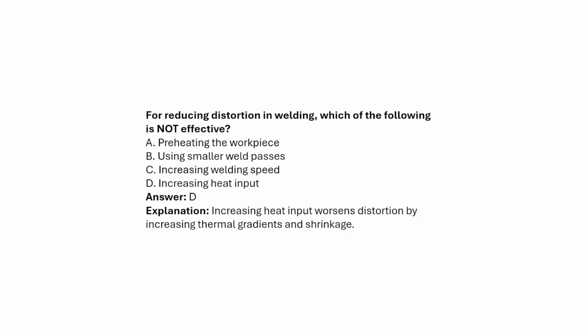If we increase the heat input, that will result in an increase in the distortion. So the answer will be option D. Increasing the heat input worsens the distortion by increasing the thermal gradient and shrinkage.